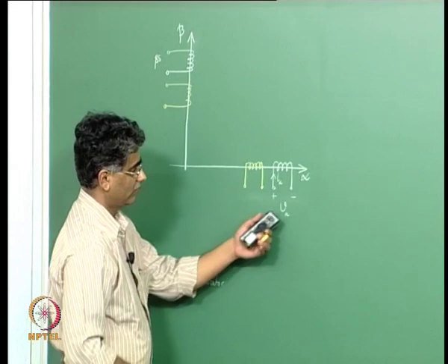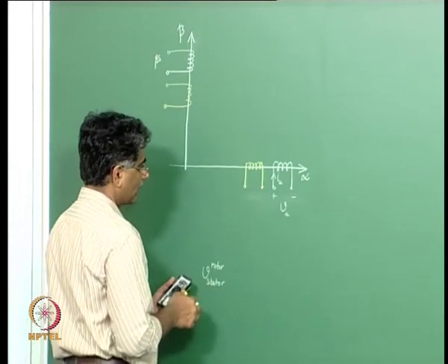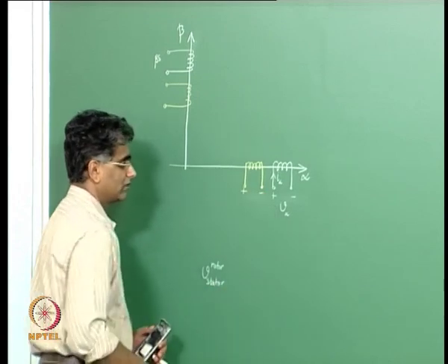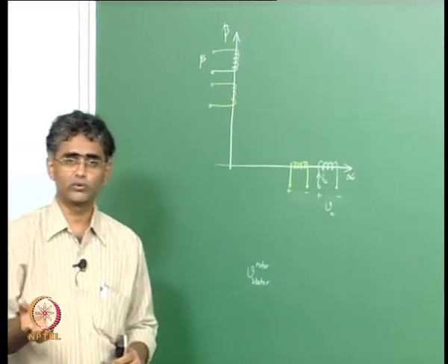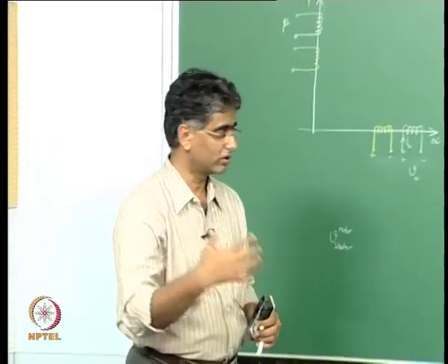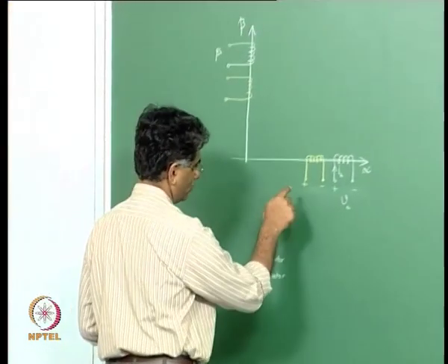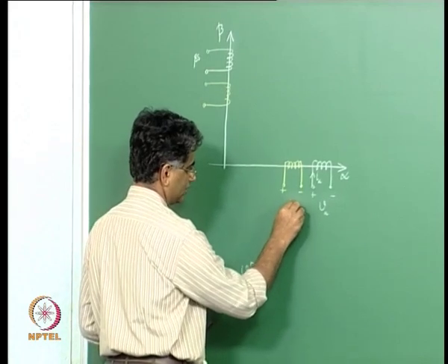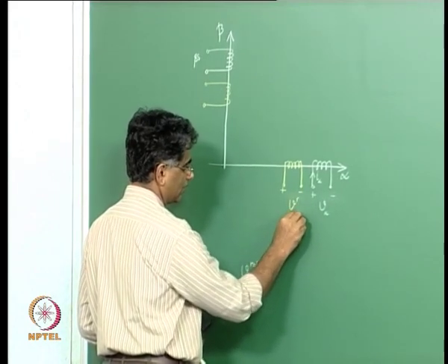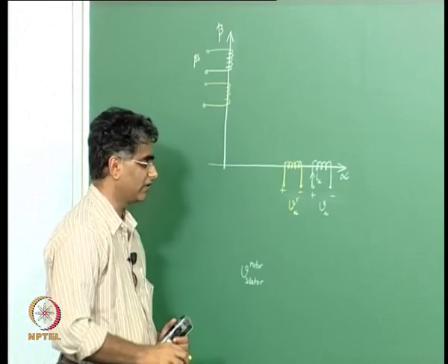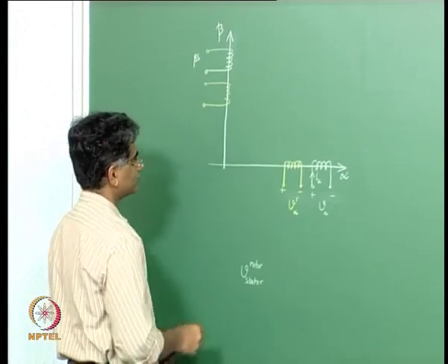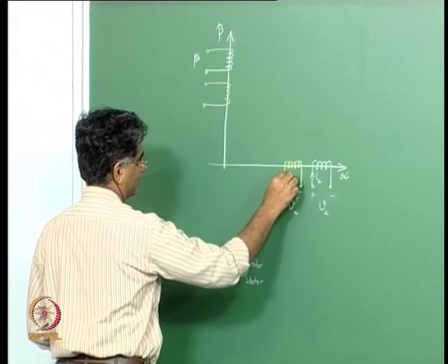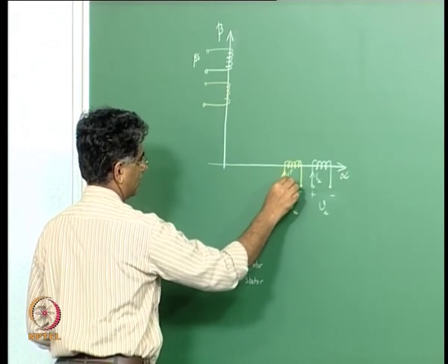As far as the rotor is concerned, both the alpha beta variables which were in the rotating reference frame of the rotor have an influence on what is V alpha here. Therefore we denoted this by the symbol Vr, but on the alpha axis of the stator, and you have a flow of current here, that is I R alpha.